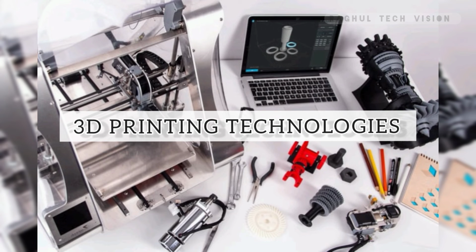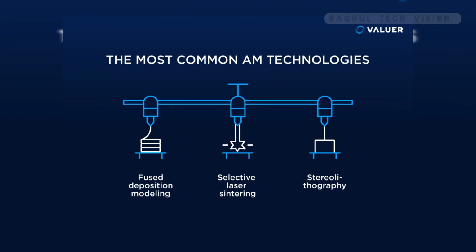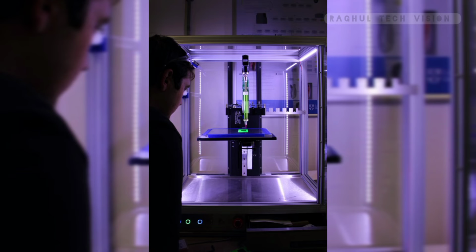3D printing technologies. There are three broad types of 3D printing technology. They are sintering, melting, and stereolithography. Sintering is a technology where the material is heated but not to the point of melting to create high resolution items. Metal powder is used for direct metal laser sintering, while thermoplastic powders are used for selective laser sintering.